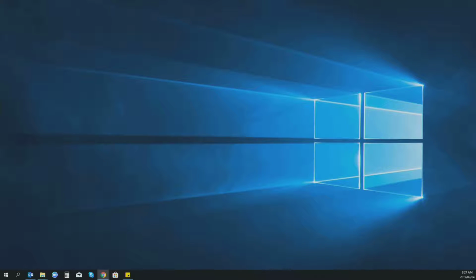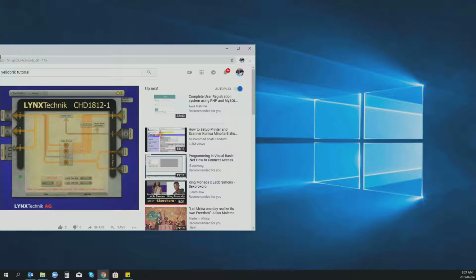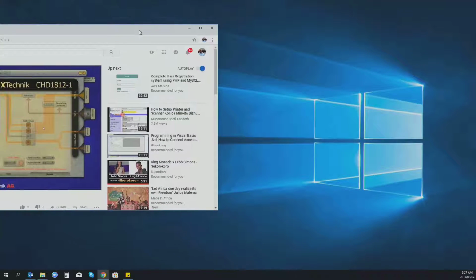And also the audio is delayed to match the video. So if you've set a manual delay up, the audio is obviously delayed to match that. And again, as we're chopping frames out or adding frames into frequency lock to the reference, obviously the audio timing is maintained. You're not going to get a drift of audio timing and lip sync problems or anything like that.